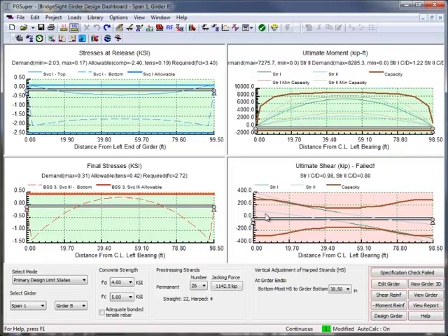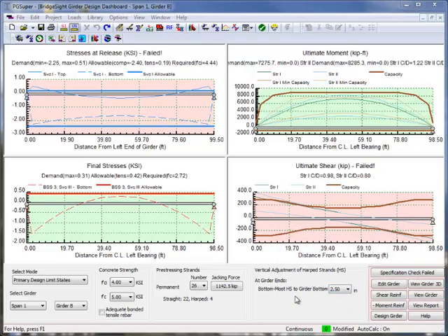As we saw before in the girder view, our current design has a relatively low level of prestressing and a minimal required concrete strength. Maybe we can fine-tune this design. As we might know, most precast manufacturers prefer not to use harp strands if they don't have to. Harp strand designs require more labor and cause safety concerns in the plant environment as compared to an all-straight strand design. So let's see if we can straighten out those harp strands using the girder design dashboard. First, I'll straighten out the strands by lowering the harp strand bundle at the ends to 2.5 inches from the girder bottom. This will make the strands straight.